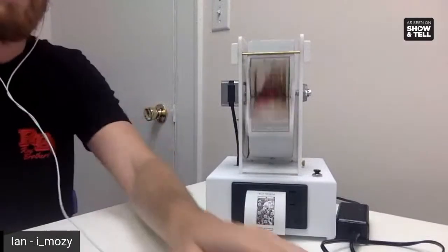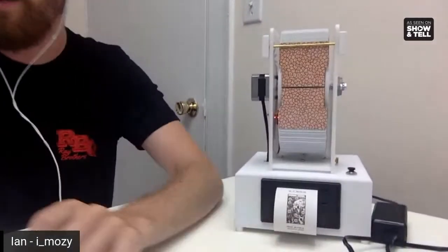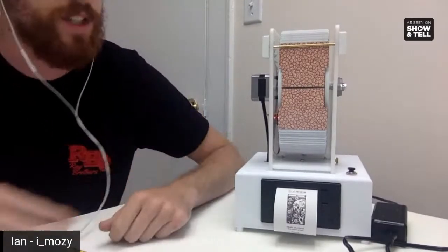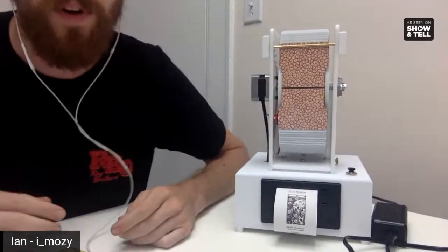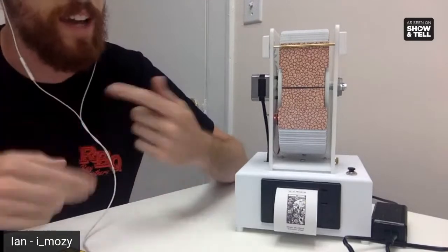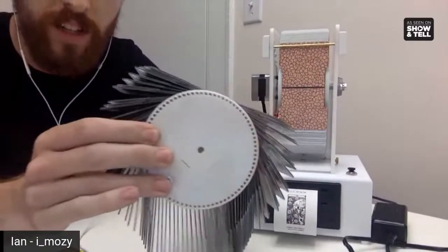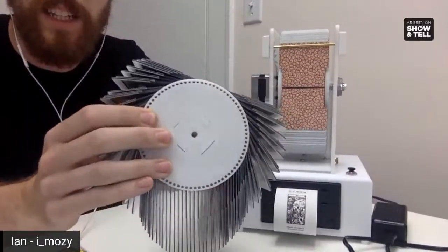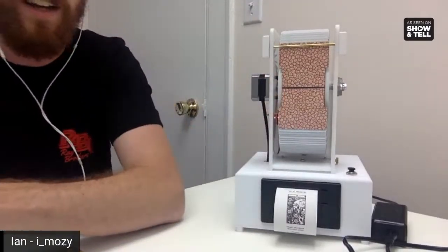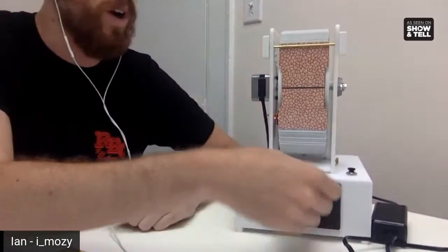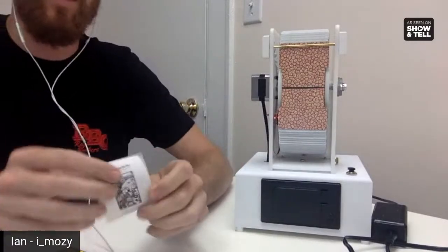Tell us more. So basically, I have the stepper motor here and it runs in a micro stepping mode. Normally a tarot card deck has 78 cards, so what I did was I added an extra 2 because you need a home card, and then I wanted to make it an even number. So basically it comes down to dividing the number of steps by the number of cards in the flaps. This is the spool here you can see from another version. And so every 20 steps, the machine goes to a new card. That way you have a number assigned to each card, and that's why the printer knows what your reading is.